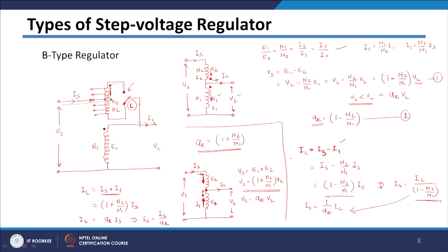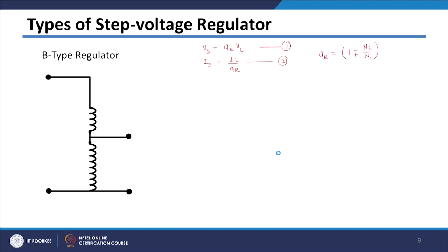So, here we are getting minus sign when we are setting it in raise position, and in case of lower position we are getting plus sign here in both the cases. So, that is why I am writing minus plus instead of plus minus, and this decides how much voltage is getting increased or decreased.